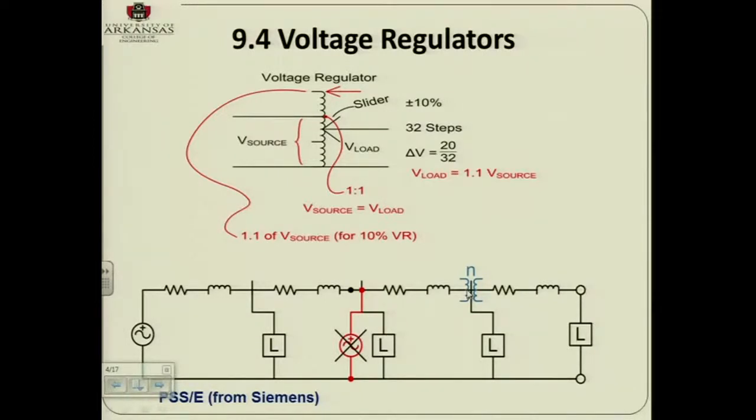Now, what is the voltage at the end of the feeder? It has to be greater than 95%. If that voltage here at the end of the feeder is below 95%, what's happened? You do not have voltage regulation. You are not within the region in table 1, which is called favorable zone, range A. If you go to table 1, there you have the favorable range. So if you are not there within the plus minus 5% here, what you do?